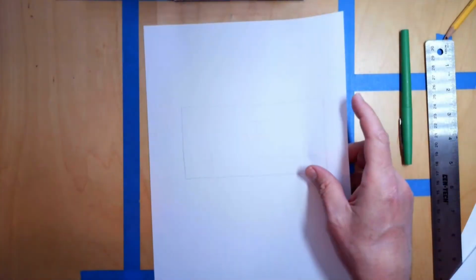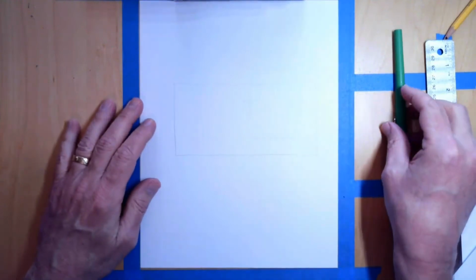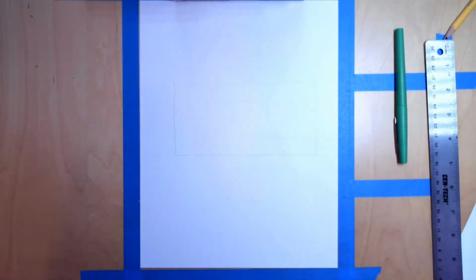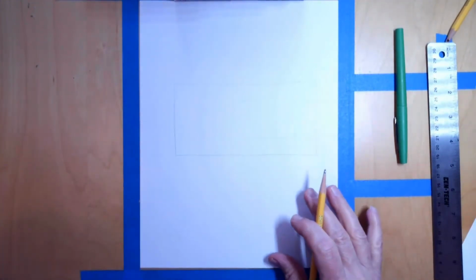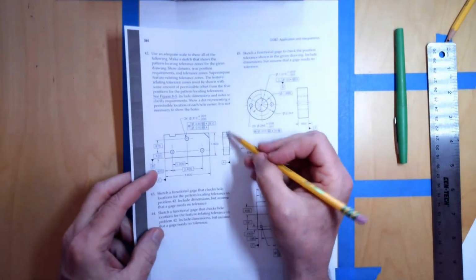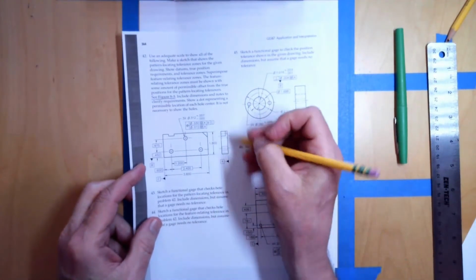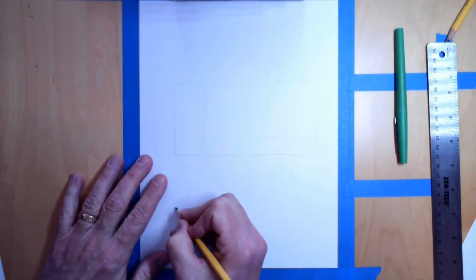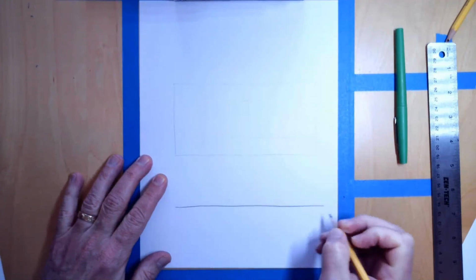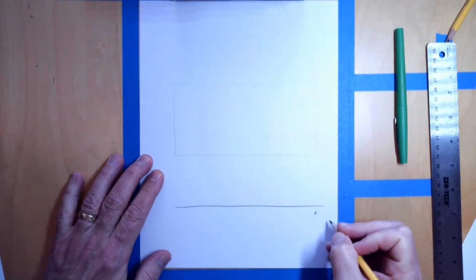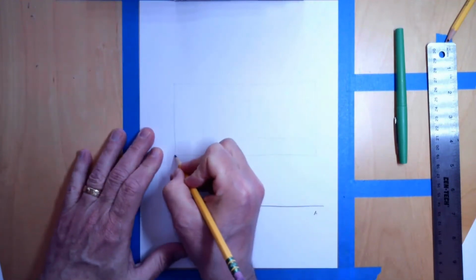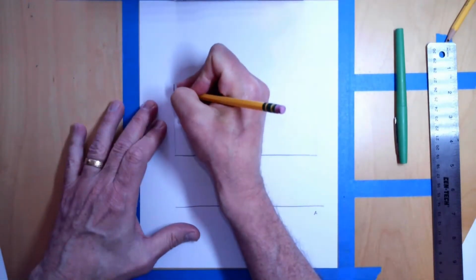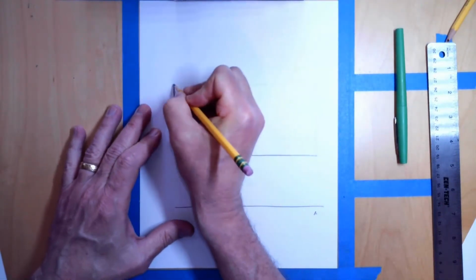So let's look at the first functional gauge. Okay, so the first functional gauge, and I have here an outline. It's a little bit light, but I'm going to show the functional gauge. So the functional gauge, we want to show the datum simulator. So we have A is the bottom surface, which I can show right here. All right, this is A. And then B is the long side. So my functional gauge is going to have a wall right there. And C is my short side right over here. My functional gauge is going to be like that.